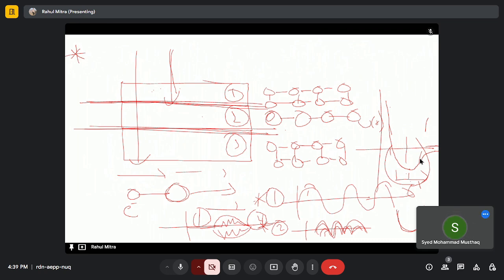And the phonon lifetime. Phonon, not photon, which is the light particle, right? The phonon lifetime is modified due to the phonon interaction with free surfaces and grain boundaries, if you are talking about alloys. Now, 0D structures have a phonon bottleneck because phonons cannot transport, and one-dimensional nanomaterials behave as a phonon waveguide, right? Because the phonons cannot substantially move from one CNT to another, they have to move in this direction.